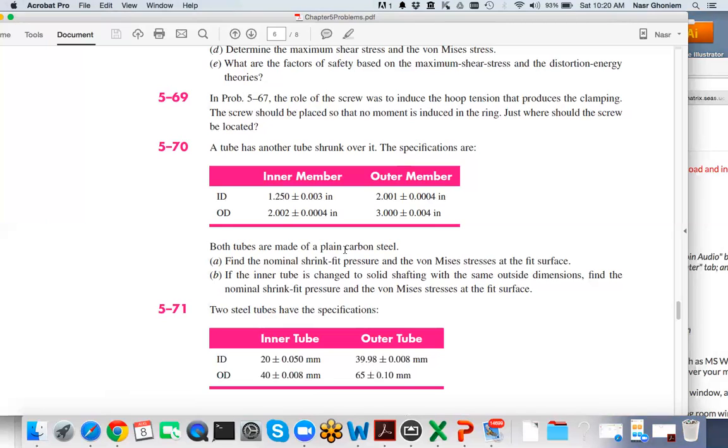As the pressure is imagined to be there, we can treat both the shaft and the flywheel as pressurized discs or pressurized cylinders. Therefore, we can use solutions from the equations of pressure vessels and pressurized discs and cylinders, and compute the stress system.